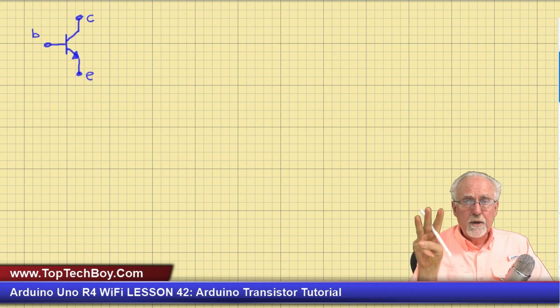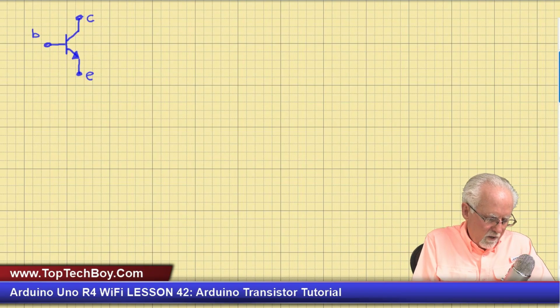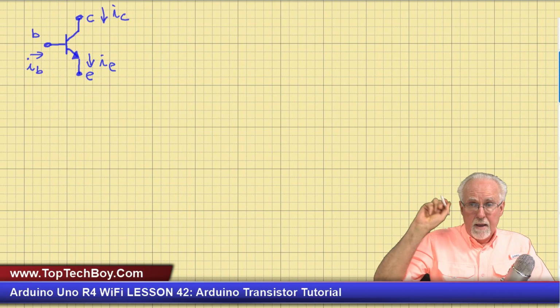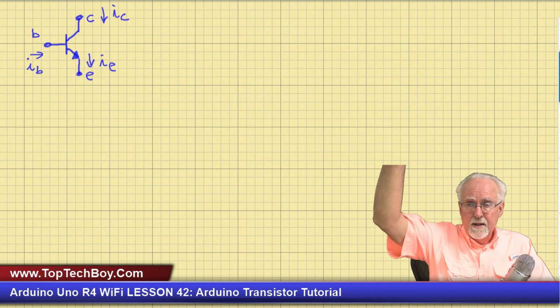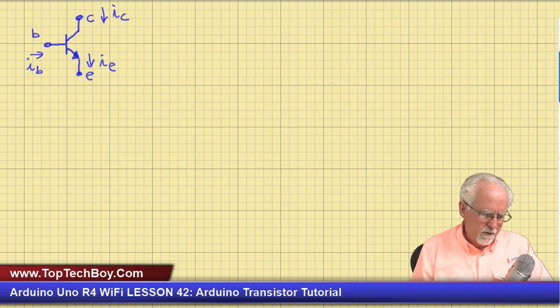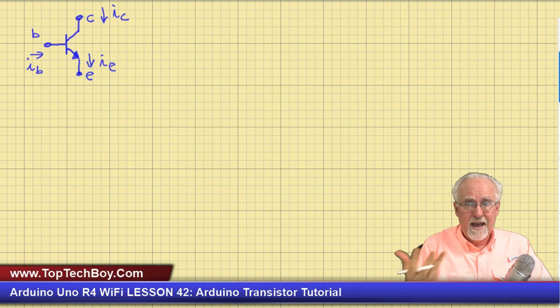Now there are 3 legs, so we have 3 currents. Coming into the base is IB, the base current. Coming out the emitter is the emitter current. And coming in the collector is the collector current. So the base current goes into the transistor, the collector current goes into the transistor, and the emitter current comes out of the transistor. And all 3 of those have to add up.